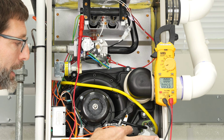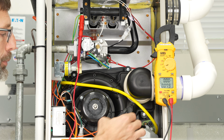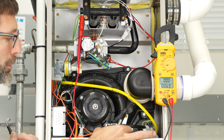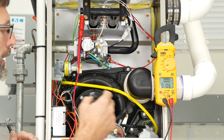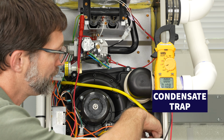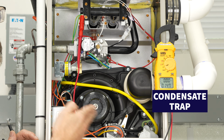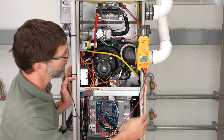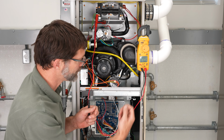Now, just because this is not closing, even with this tube connected, it does not mean that the pressure switch is the problem here. And so you could take another instrument in order to test this outside of the furnace, you know, a different manometer that has a pump on it. You could have another issue such as back here, there is a condensate trap, and that could be the problem. That could just be clogged with water. You want to think of the simplest things first. And so it has a drain that drains down. You could take a shop vac down here and suck that through.